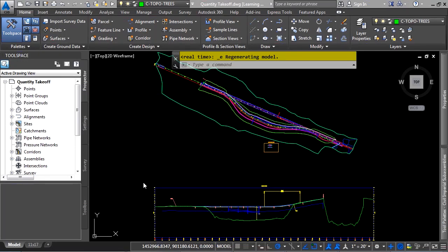In this video, we will discuss quantity takeoffs. If you'd like to follow along with this video, please open the file quantitytakeoff.dwg located in the training folder, as discussed in the Working with this Dataset video. You can add quantities to your drawings using Civil 3D's QTO Manager to apply pay items to AutoCAD Civil 3D objects or regular AutoCAD objects.